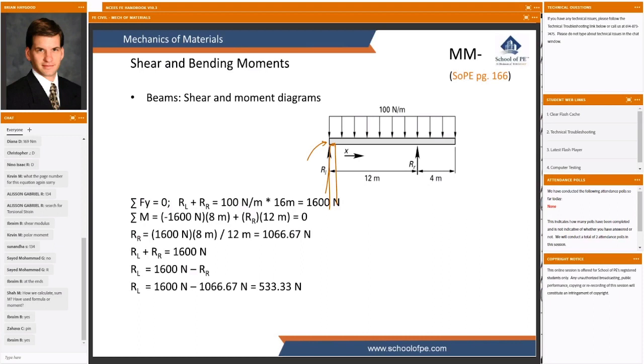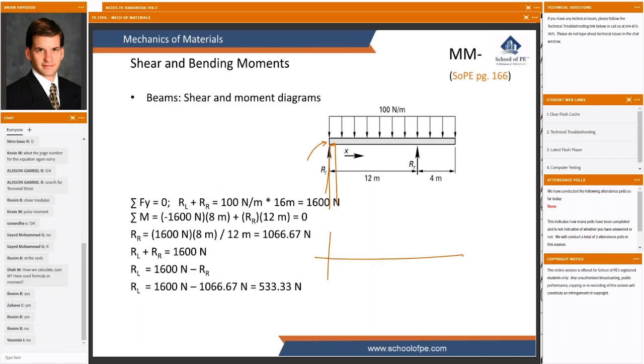Is there any force on the end of that beam that's trying to scrape the paint off the end of the beam? Like that far left-hand edge, is there anything shearing that off or anything trying to scrape up the side of that beam? No. So when I start my shear diagram, I can pretty safely start it on the left-hand side at 0, if I think that's what that support represents.